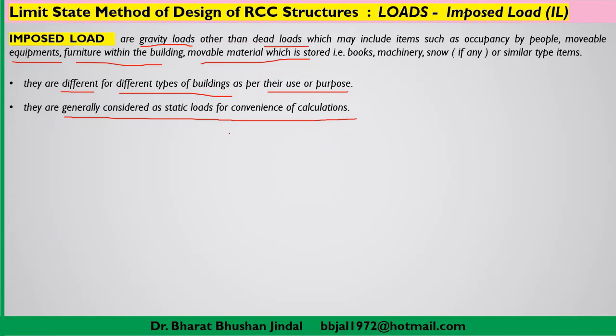There may be a little bit of dynamic effect of imposed load also, but for the simplicity of calculation, we are not going to take that dynamic behavior into consideration. So you can consider, while doing the design calculations, that dead load as well as imposed load are both taken as static loads.